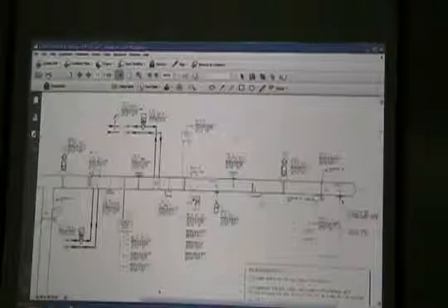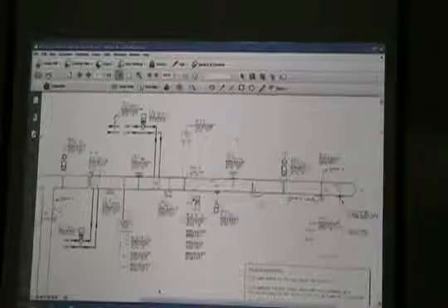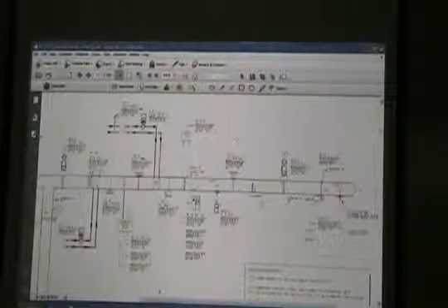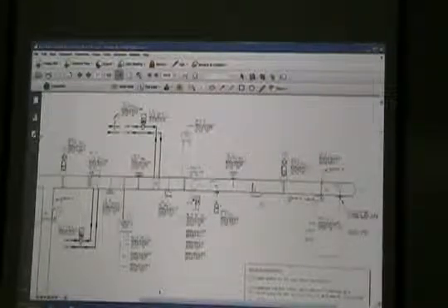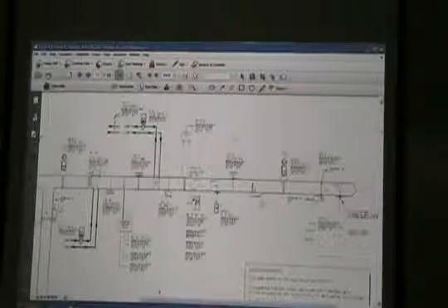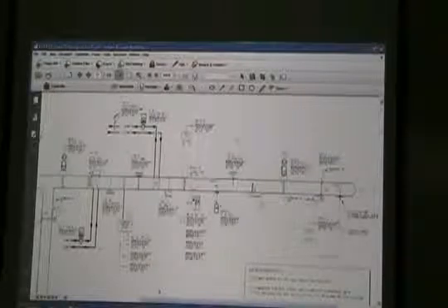Okay, so we're looking at a discharge temperature sensor right there, which is an analog input into our controller. We're always monitoring the duct supply temperature. So back through the controller, we're telling that valve to modulate to maintain that temperature right there.